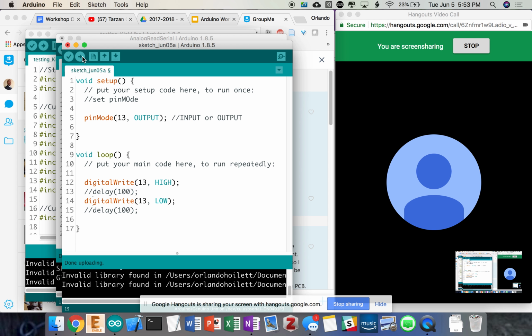I assume the analog pin out actually has a lower voltage. No, we talked about multiple things there. The digital pins do pulse width, and they do a full 5 volts or 0, and they just change how long it's on. Then you have analog output pins, which are digital-to-analog converters, and those are separate. Those need to be arranged individually on that scale.